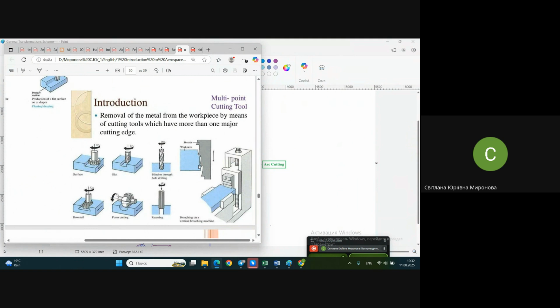Of course, everything has limitations. This process is typically used for complex shape cuts and for higher quality demands. It's not the only way to make rectangular holes, triangular holes, but in conventional machining broaching is practically the only way. May we do it by milling? Yes, we may, but milling will leave some fillet in the corners. In case you demand zero fillets, or practically zero fillets, you may do preliminary milling or drilling, but next we go into broaching and maybe finally even additionally abrasive cutting.